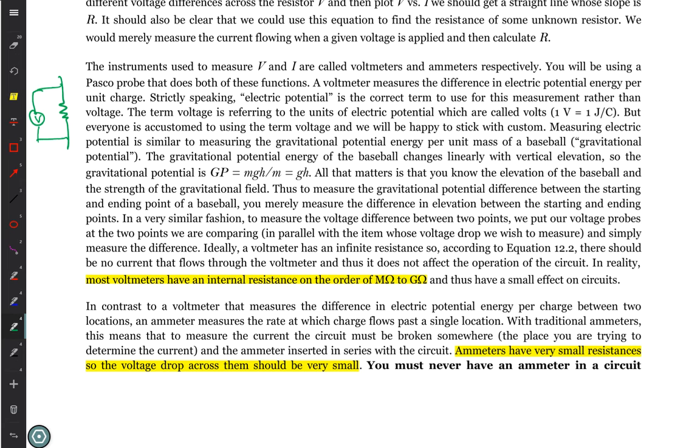So you can see I've highlighted up there that most voltmeters have resistances that are mega ohms to giga ohms. So if you're using, like in class today, we're using about 1 kilo ohm, about 1,000 ohms. If our voltmeter has a resistance that's a giga ohm, a billion ohms, 1,000 versus a billion, there's going to be virtually nothing that goes through the voltmeter, so it makes very, very small, like, 0.0001% difference. With our work, you know what? 0.0001%, not a problem.